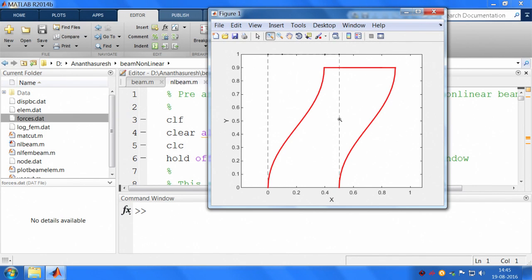Later on we will learn more about nonlinear finite element analysis, what it actually means, right. Now we have this. So if I have this one as the stage that is supposed to move purely in the x direction, I am not getting it here. When I do nonlinear analysis, which is actually realistic, it is moving down. In order to compensate for that, we add 2 extra beams, which is what we had originally when we opened the file. So let me go back and put those files and then see what happens.